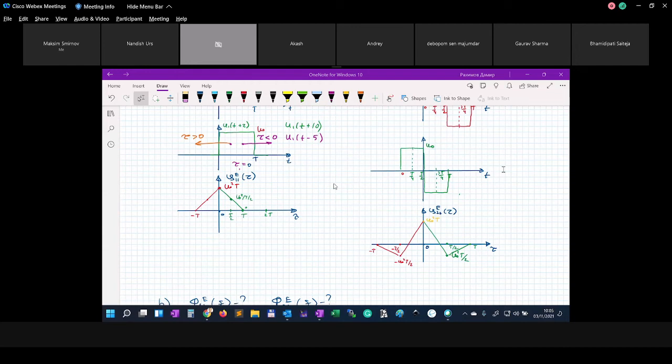You could imagine that it's not necessary that you are limited in time, but if you calculate energy for this signal, it will be finite. If you take a periodic signal and simply integrate from minus infinity to infinity, the result will be infinity. This is a problem you have to be able to handle. But we can also do this by normalizing by the period.